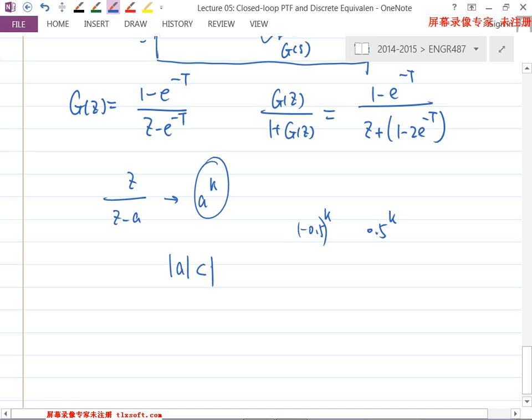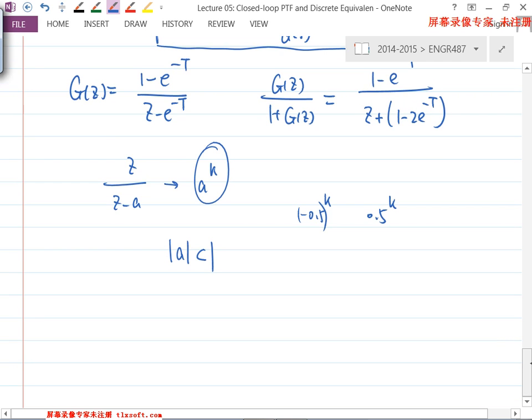And that's actually what we're going to learn. Basically, when the poles of the discrete system are within where? Within the unit circle, right? For discrete systems, in your DSP course, you learn that. And this is closely related to the left side of the S domain. So in one of the courses, we'll learn the mapping from S to Z. And the other thing to talk about for now is the difference between these two here.